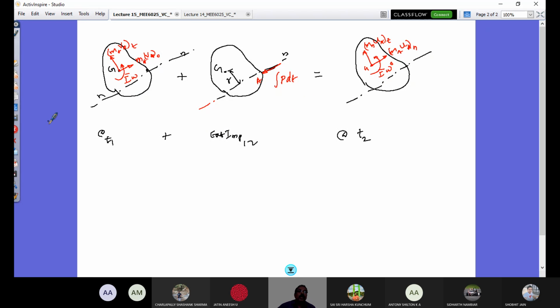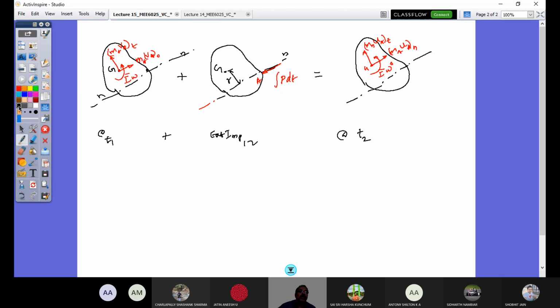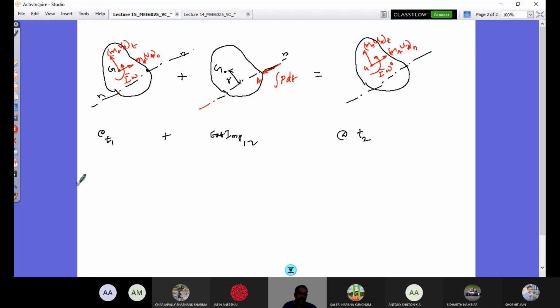So now if I apply my angular impulse and momentum principle, what should I do? I should take moment about a convenient point, and the convenient point here is point G. So taking moment about G, what will happen here? There is no moment by these two forces because that passes through the line of action of these two momentum are at G itself. So that won't participate.